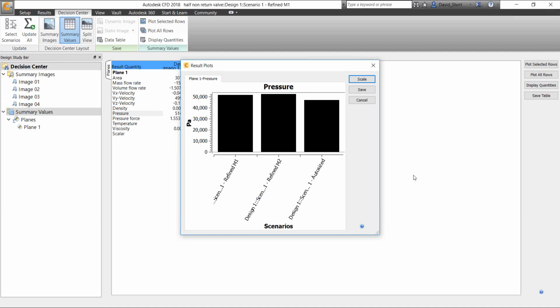You're going to end up trying a bunch of different things, and this just lets you only have to assign the inlet and outlet plane once, and then it's there. You can run as many scenarios as you want, and you can just update the summary value and figure out your pressure delta. It lets you eliminate bad approaches quickly and keep the good ones.